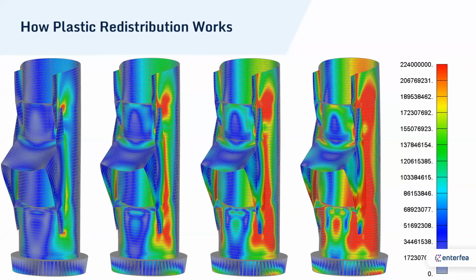So what you see here is the actual outcome from nonlinear FEA. And you can clearly see that from the left, the load is low, to the right, the load is high, right? And this is where most people using FEA stop. And my question is, okay, so when did it fail? On the left, the load is low. On the right, the load is high. You have some in-between outcomes.